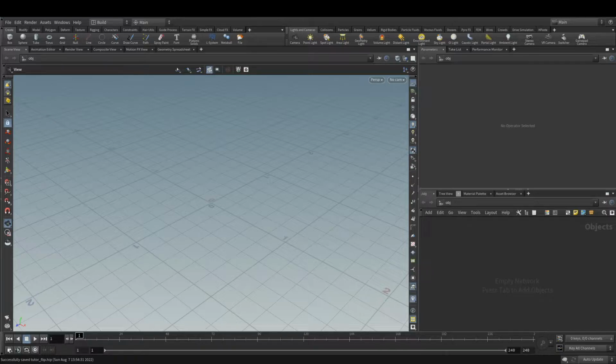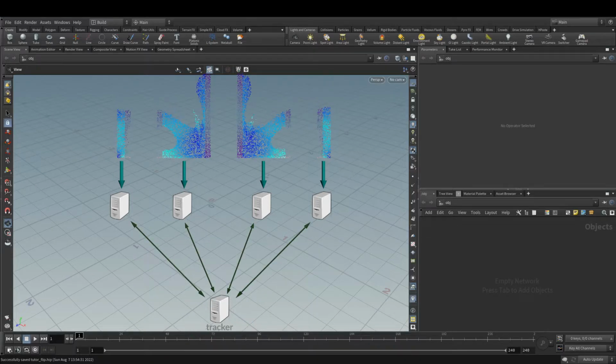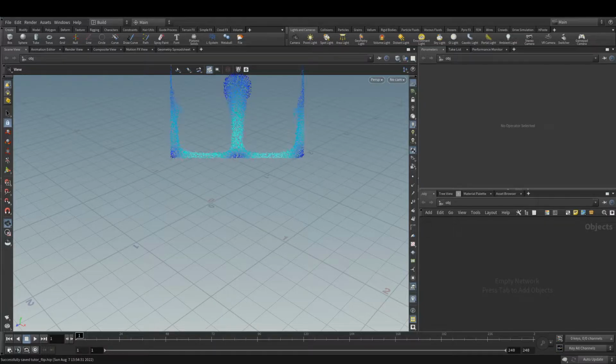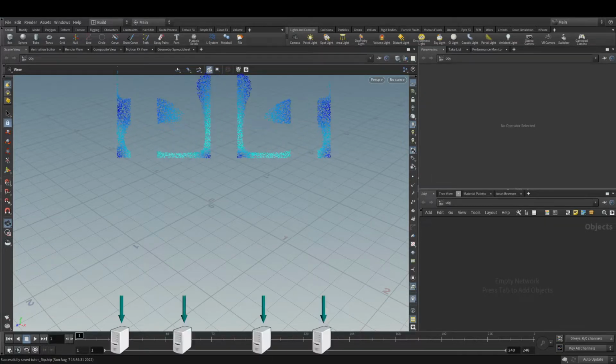A quick reminder about Houdini's distributed simulations. Houdini has a way of running some simulations, such as Flip and Pyro, distributed over several computers. This is done by splitting the main task into slices, parts of the original problem, that are solved usually for one time step on different machines independently. Then slices synchronize and exchange border information over the network, then the next time step is solved, and so on. This setup requires a way for slices to synchronize after each slice has finished its time step.